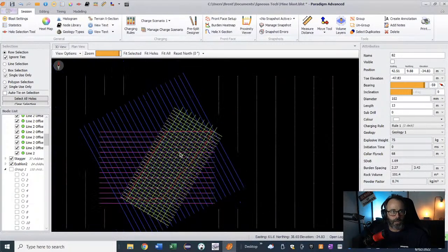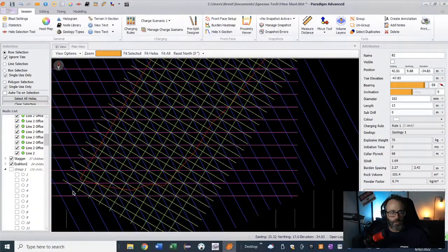I hope that you all enjoyed this as a concept. And you can see, if I turn off these blast holes there and put the screen back on, you can see the gridding method. You just got this grid. So if you're concerned about where you put an infill hole and you want some logical reason for moving it, then move it along those lines. Slide it up the echelon line, or up the reverse echelon line, or along the spacing, or back through the stagger of the pattern.